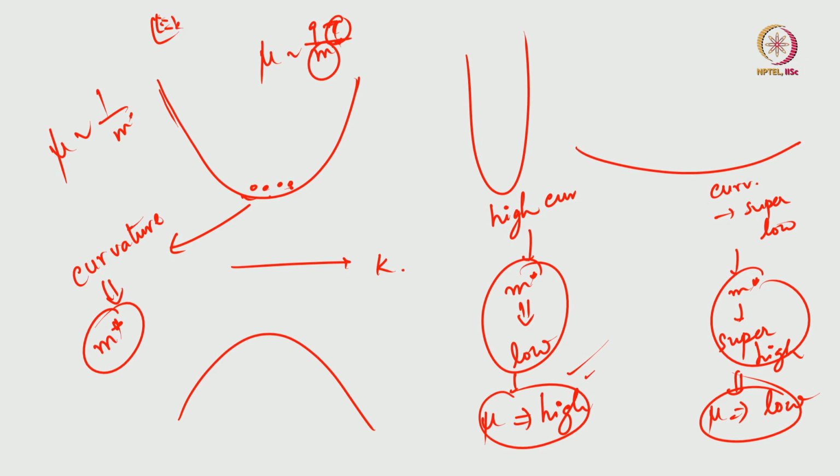This phenomenon of negative differential resistance, which comes about from the electrons jumping from one valley to another valley at sufficiently high field, is the reason for microwave oscillation. But in this case it is a little bit more complicated than a tunnel diode, because there is something else in between the negative differential resistance you get because of the different valleys and the microwave generation. That is called domain formation in gallium arsenide. We will talk about domain formation in the next lecture, but here I just want to show you that using the different valleys of gallium arsenide, you are able to generate a negative resistance, and that is the physics of this material.